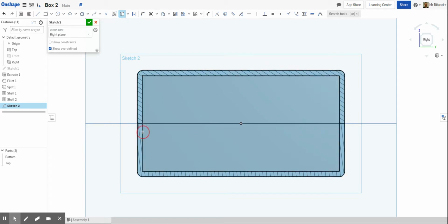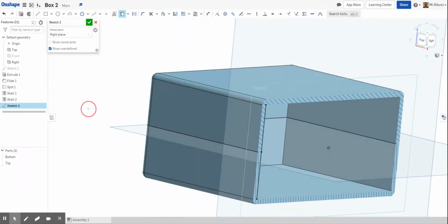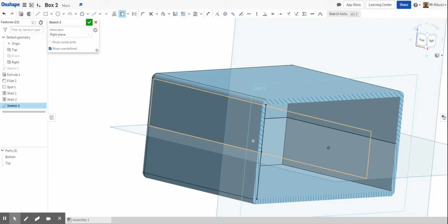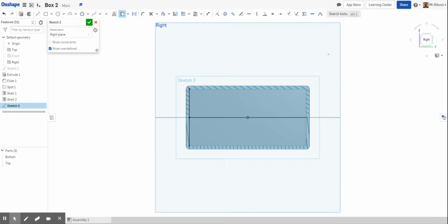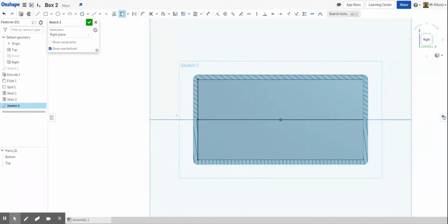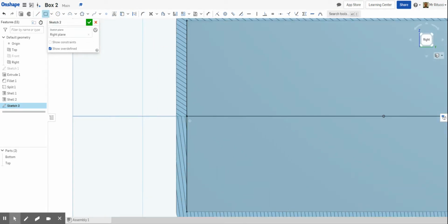and this line here. And if I just spin around the view, you can see that it's projected those lines onto this work plane, which I'm going to use as a reference. What I'm going to do now is use the corner rectangle tool, and I'm going to draw from here my part that's going to create a little shelf. So I'm going to click that. And the reason why I use that geometry as a reference is because it allows me to find this point